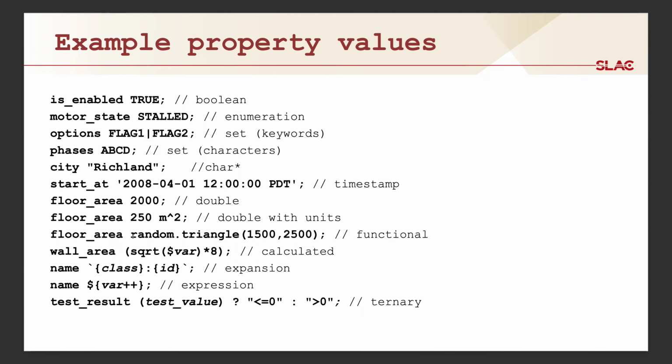So it gives you a way of initializing a particular property using a random distribution without having it change later, as we'll see with the random var property. This is good for doubles and complex values. It allows you to set them and initialize them with some randomization and then leave them alone from then on.